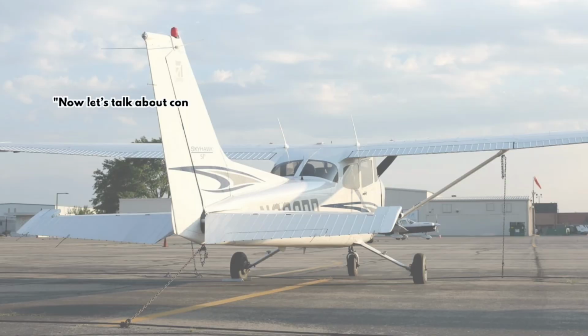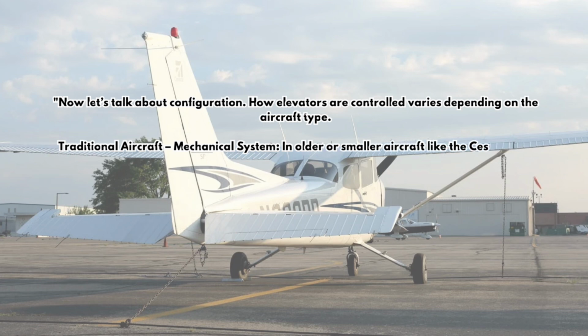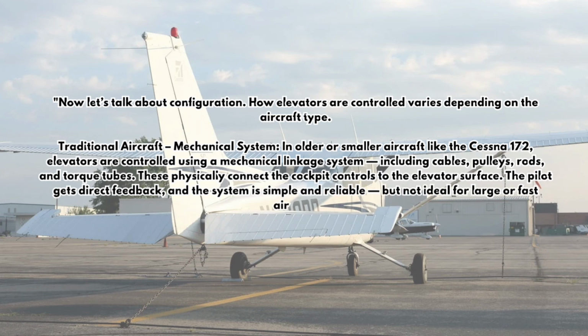Now let's talk about configuration. How elevators are controlled varies depending on the aircraft type. Traditional aircraft, mechanical system. In older or smaller aircraft like the Cessna 172, elevators are controlled using a mechanical linkage system, including cables, pulleys, rods, and torque tubes. These physically connect the cockpit controls to the elevator surface. The pilot gets direct feedback, and the system is simple and reliable, but not ideal for large or fast aircraft.